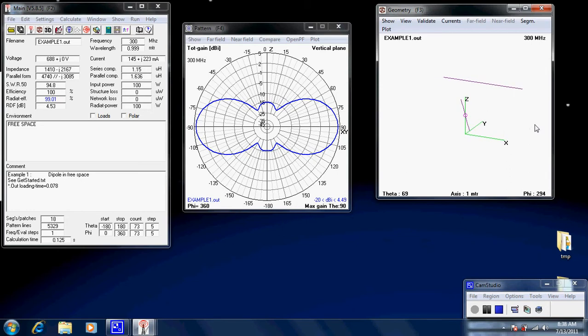The way that you actually enter information into the editors is in three dimensions. You have to define an antenna as a point in three-dimensional space. We use the three-dimensional coordinate system, x in one direction, y in the other, and z as the height. So that's all there really is to it. Each wire is defined as a beginning and an end. Each end of the wire will have an x, y, and z coordinate, and the other end another x, y, and z coordinate.